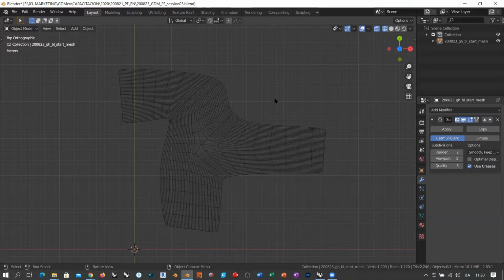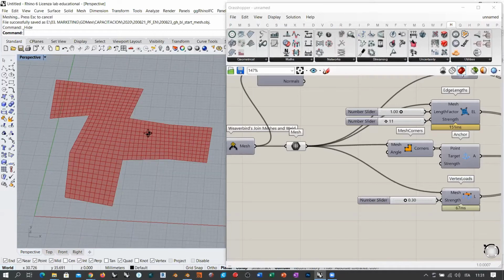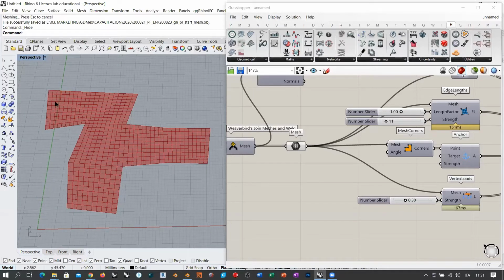Normally, the aspect ratio for, let's say, a homogeneous deformation should be 1 more or less, which means the width by height of this rectangle should be more or less the same. So an aspect ratio larger than 1 or smaller than 1 tends to create irregular polygons like rectangles. It is best to work with aspect ratio 1, which is what we were doing here in the Rhino mesh or Grasshopper mesh, because you see that these look more like squares.